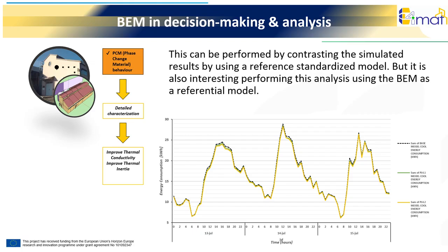In retrofit scenarios, BEM is particularly valuable because it allows practitioners to test different renovation strategies, such as adding insulation, improving glazing, or modifying system controls, without the cost and disruption of trial-and-error interventions on the actual building. For instance, it allows the assessment of an optimal thickness of a layer, as well as its position inside the different layers in a construction.